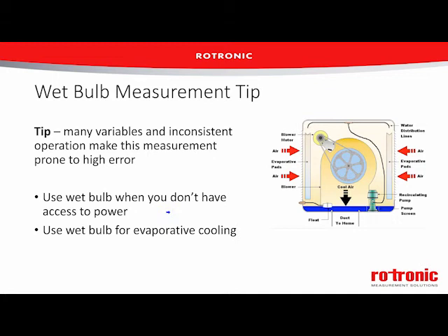Thanks. So we see wet bulb temperature used in a couple different places. Sling psychrometers, which we don't see so much anymore, but it still gets used in some environmental chambers. If you see two temperature sensors on them, one with a sock on it and a little pool of water, they actually can use these as the control sensors for some environmental chambers.